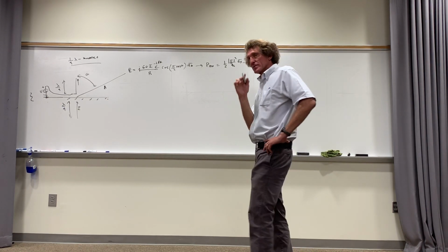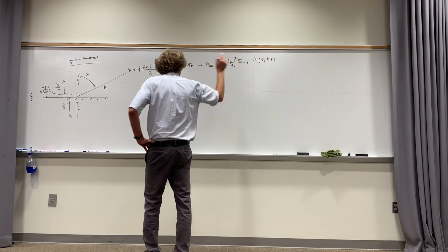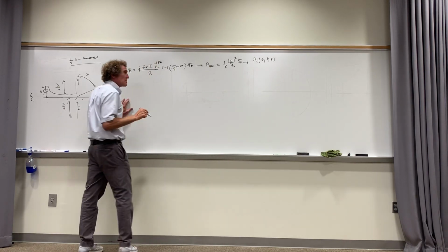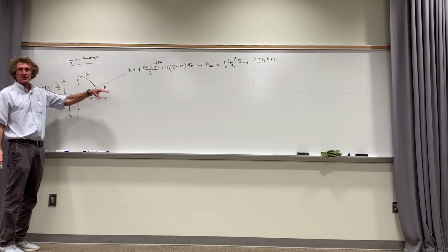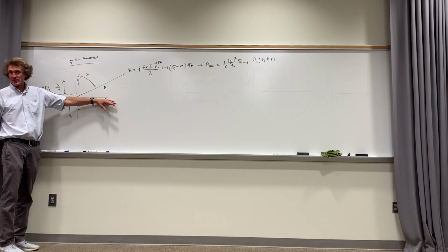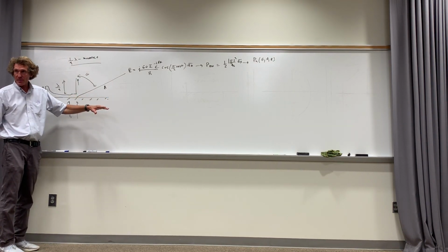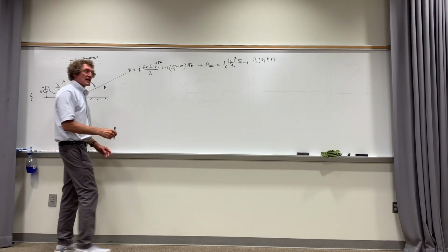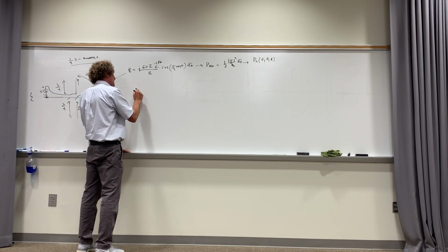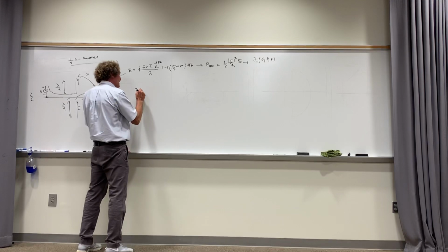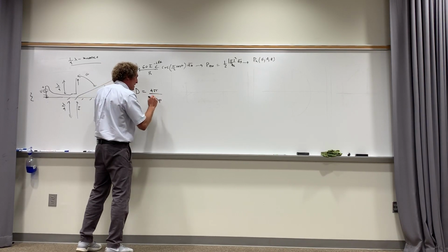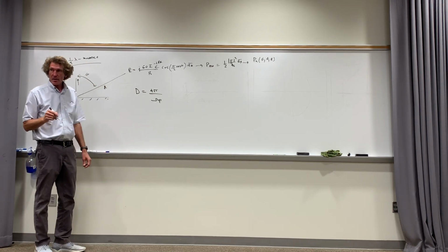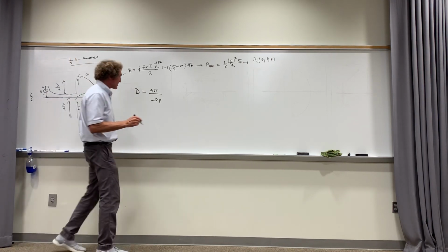All right, now this is the thing that's important. If that normalized power is the same as a half-wave dipole, but it's radiating only in the upper hemisphere, say the northern hemisphere, and in the southern hemisphere there's no radiation, then when we calculate the gain, the directivity would be equal to 4 pi over the beam solid angle. Now what is that beam solid angle?